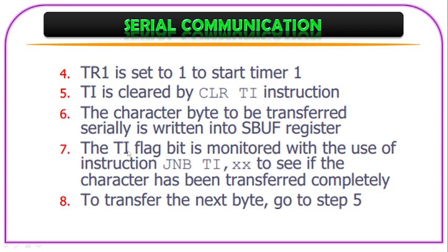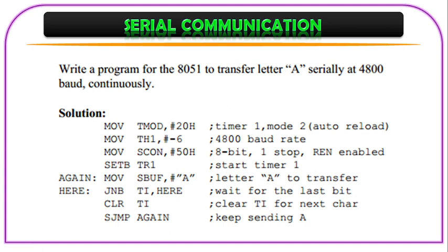And then when the TI flag is high, you have to stop it. Otherwise, if there is more data, you have to repeat it. For the next byte, you have to go to step number 5 and repeat it. So this is how you will program it. Now we'll see a few examples.